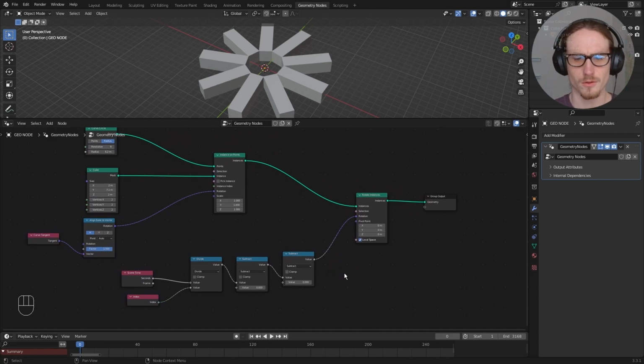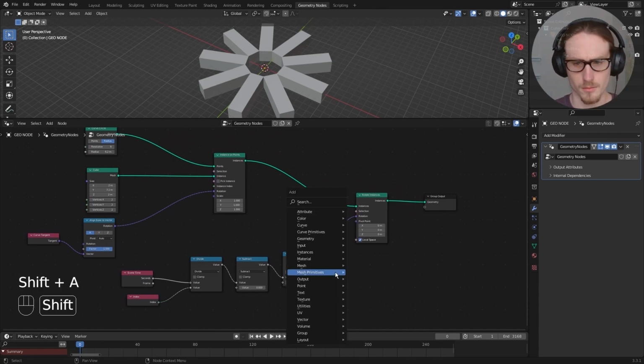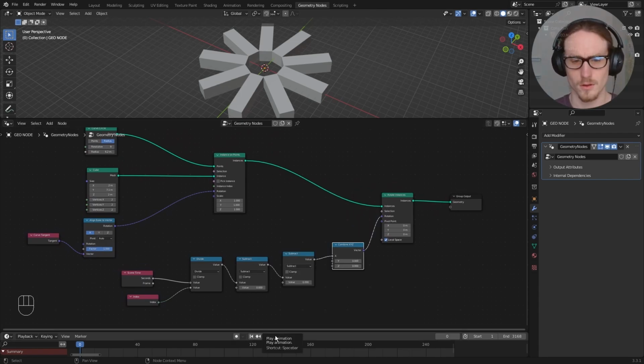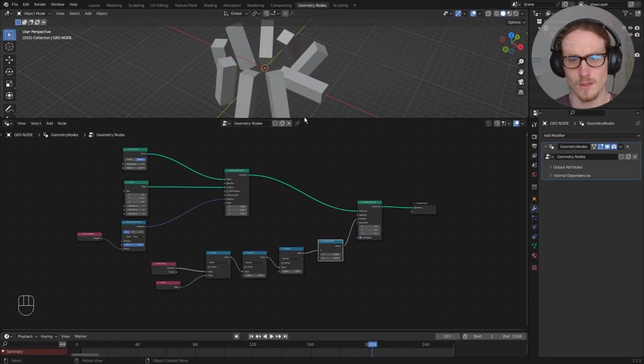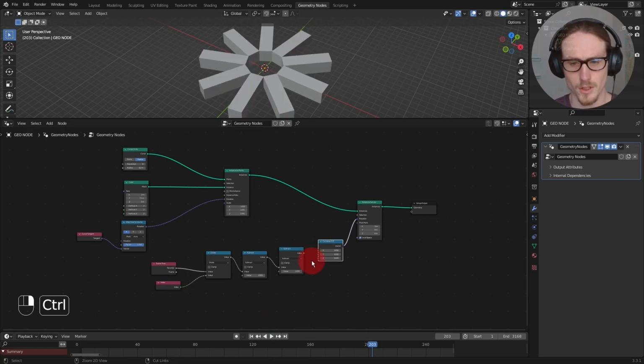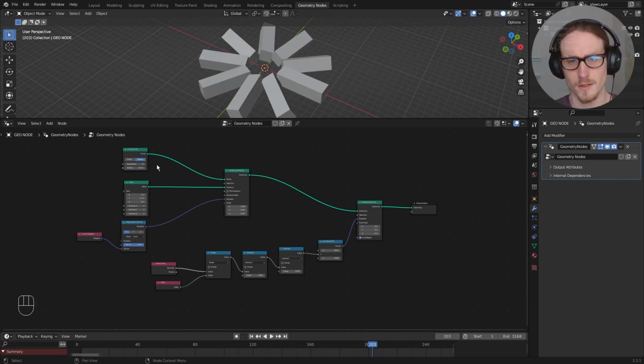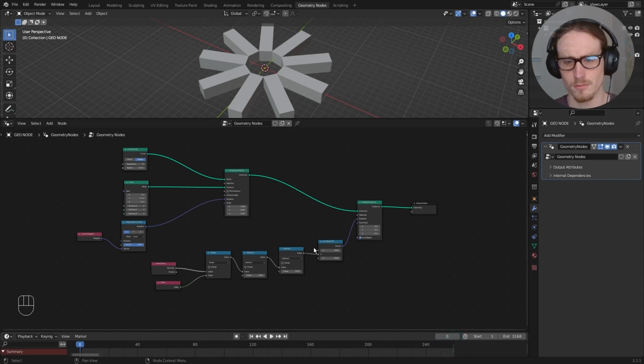The last thing I want to do to modify the rotation is add a combine X, Y, Z to be able to change the axis yet again that this is rotating around. So this is now what we want. We've isolated it on this X axis here. We can always change it to Y. It's indexing, it's staying radial, and it's rotating exactly like we want. And you can change the appearance of that by changing X or Y or even both, X and Y.